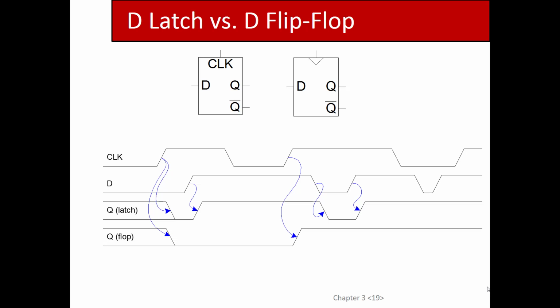So that way you can allow all the stuff that happens in your circuit to happen on the rising edge. So you have from the rising edge to the next rising edge to do your work that you have to do within that cycle, right? So everything goes from rising edge to rising edge. So you can ignore the falling edge of the clock. Now that's hard to do initially because you're like, wait, it's there, you can see it. But you just look at the rising edges.